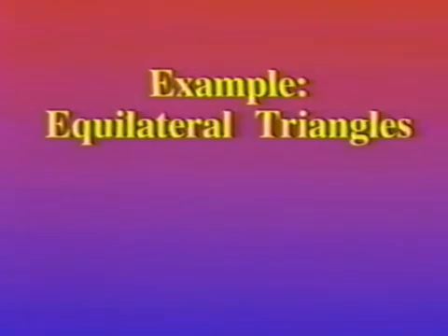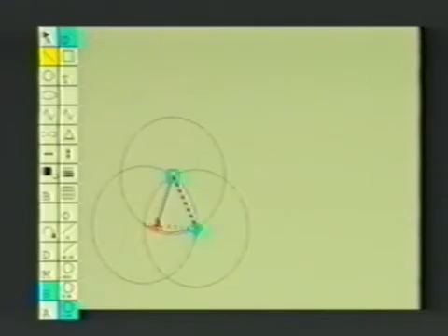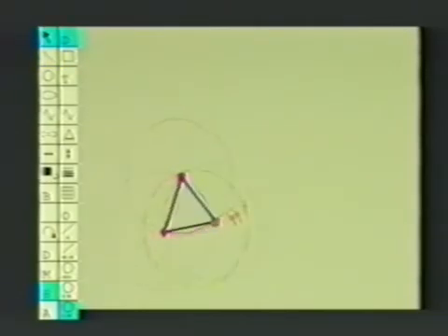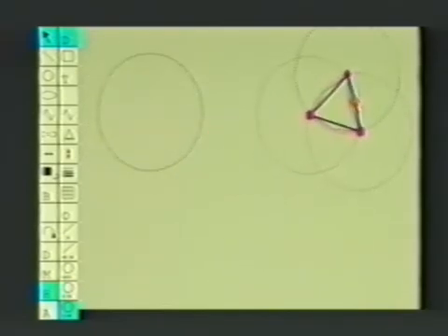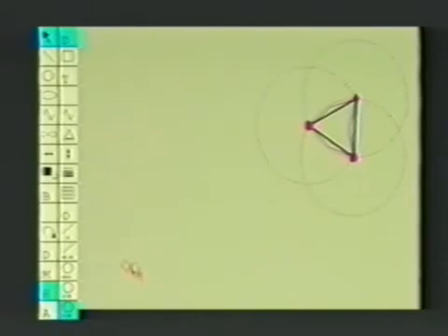Here's a standard snap dragging example. 1-inch alignment circles are used to create an equilateral triangle. Circles are created at interesting points such as where the mouse is clicked down and the ends of new line segments. By snapping to the circles, we have specified that the line segments are connected to each other and all have length 1 inch. These relationships are preserved during subsequent dragging, keeping the 1-inch equilateral triangle.